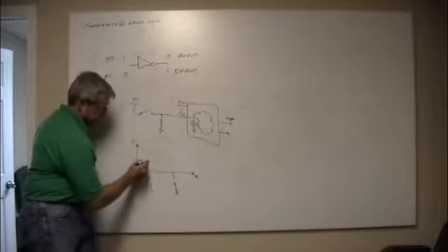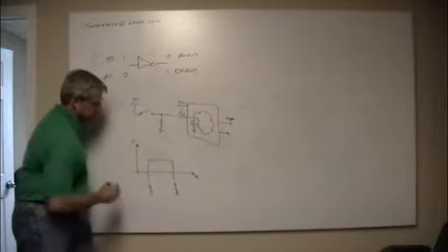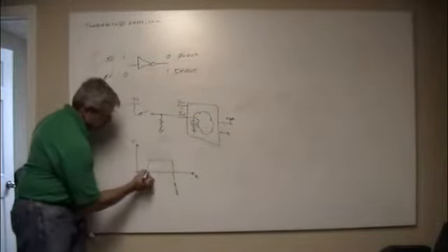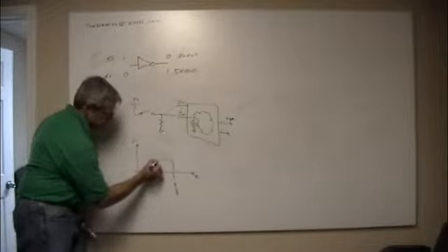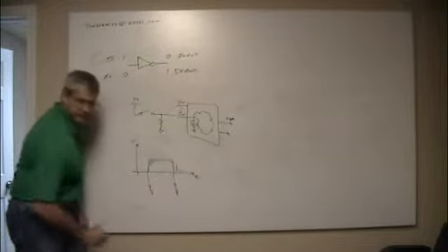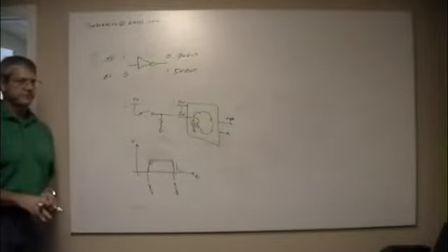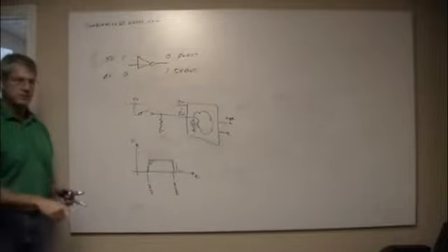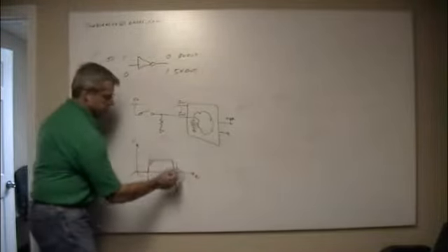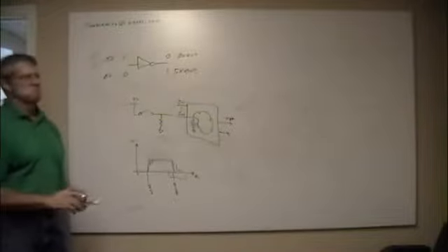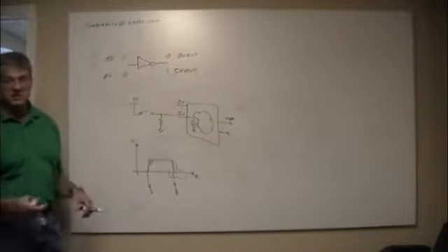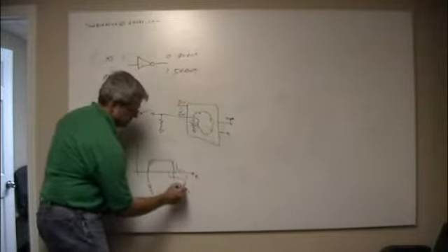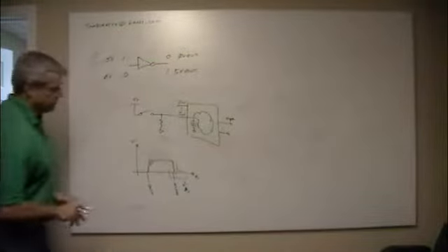Ideally we'll see this, right? What I'll most likely see is this. That's the bounce. Now, for a push button switch, this time here is usually on the order of 2 or 3 milliseconds. Not nanoseconds, milliseconds. So I want you to think about this.